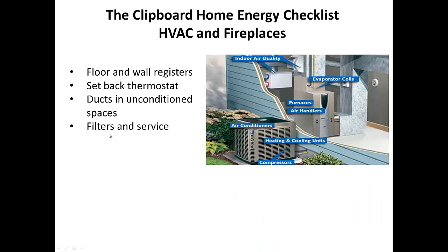Service and filters. Changing your filters on a regular basis is an important thing to do. Ideally you change your filter at the beginning of the air conditioning season and at the beginning of the heating season. I know that I'm as bad as anybody else in terms of remembering to do that, but it does make a difference. Your system will run easier, and that means you will feel more comfortable and pay less money to the man.